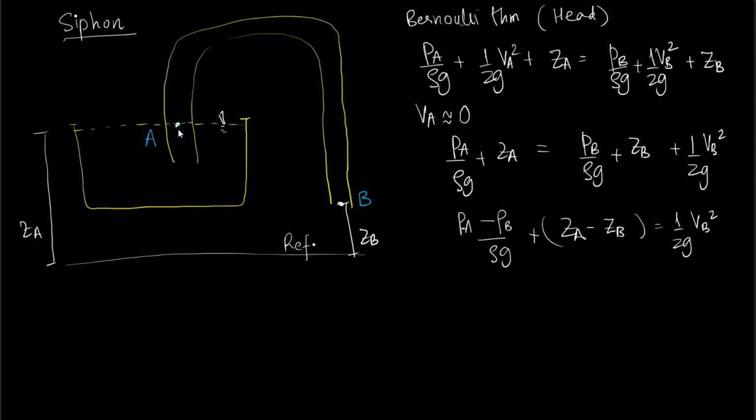Okay, so you can imagine a streamline which connects the free surface, and if you apply Bernoulli theorem between these 2 points, the velocity is negligible at both these points, the altitude is same for both these points, and the pressure is therefore equal at both these points, neglecting surface tension effects, of course.